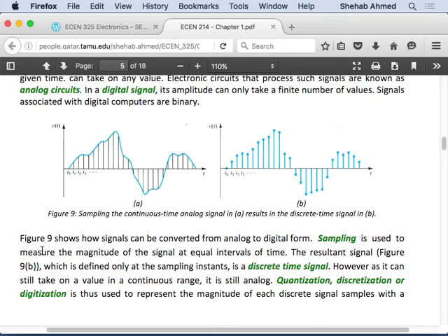No. If it's in the pass band of the amplifier, but we will attenuate it. Okay, so we will design the amplifier such that we look at the frequency domain. Any signal that is beyond 100 hertz, we will attenuate it. Any signal that is less than 100 hertz, we will make it pass. We can amplify it. We can do whatever we want.